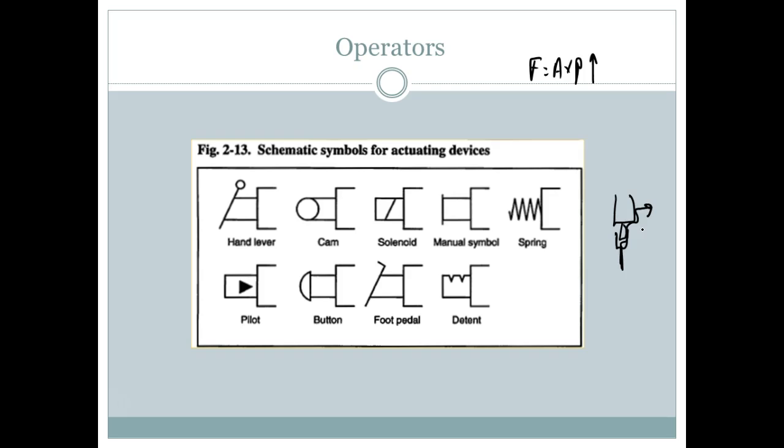Hydraulic system might run at 1,000 psi. So we can just do a little old tiny hole because all we're going to do is change the flow a little bit, but the pressure and flow are two different things, right? You understand? So I could use my little solenoid to open up a little port. That port could come up and apply a lot of pressure and do what? Shift the spool.